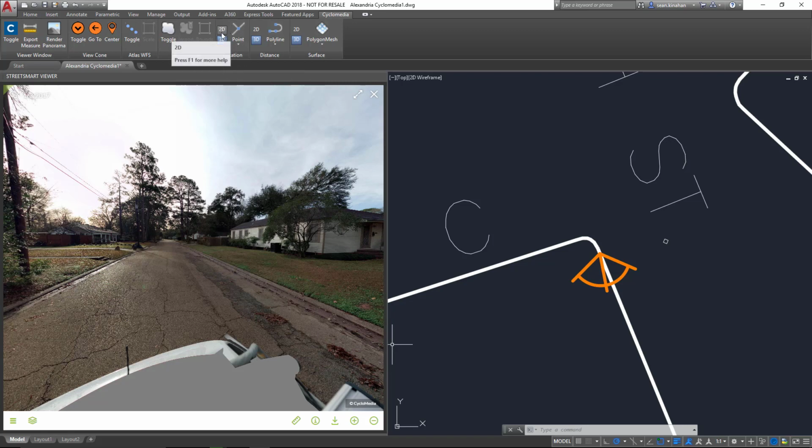As you can see, there's a 2D and 3D toggle for each of these measurement types, as well as a list of entities that can be created for that type. So for point, the options that are currently supported include creating a simple AutoCAD point, a block reference, a text annotation, just XY. For polyline, we have your simple polyline and arc, for distance I should say. For surface, we can create polygon meshes, a simple polyline, or a hatched polyline.